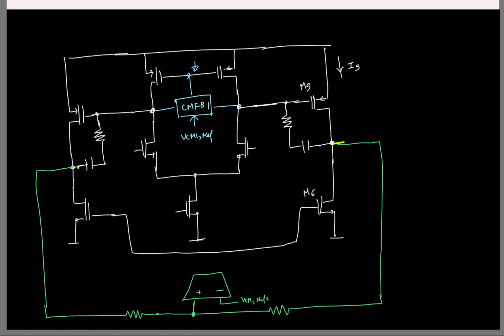Okay, and what do you think could be a reasonable choice for VCM ref 2? Both branches are similar, right? No, right? Because and MOS down. Why are they similar? Here we can set VDD by 2. It's the output common mode, right? See, even otherwise, let us say I call this output V0. What is the maximum output I can have?